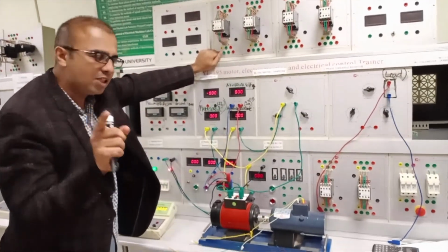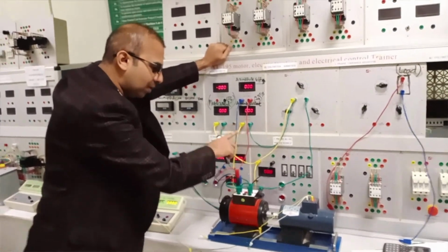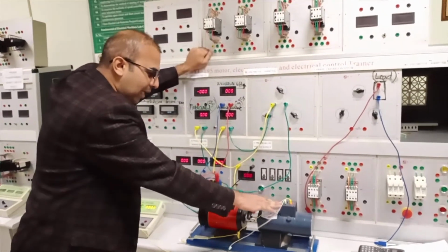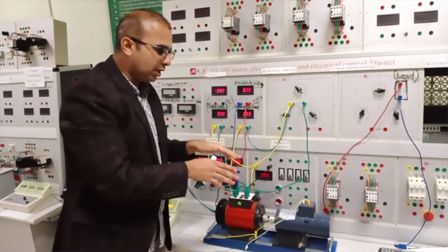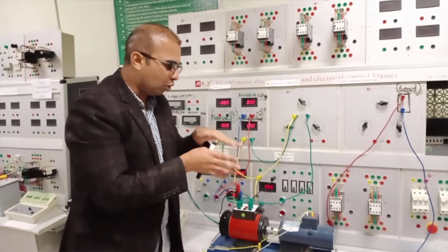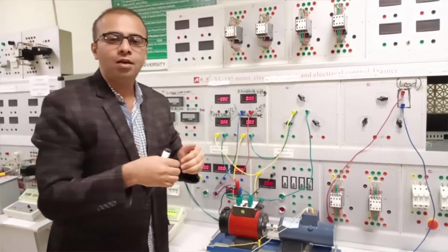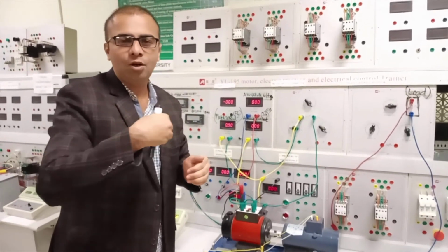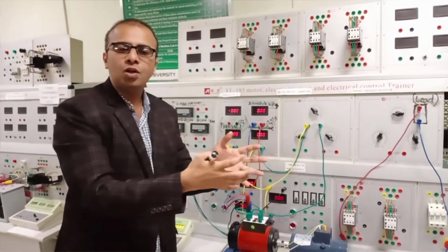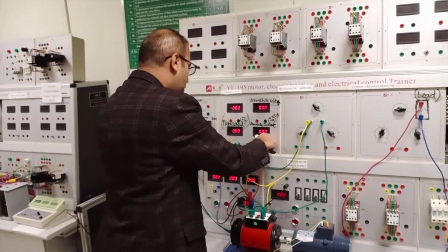First of all, we need to connect this motor with the supply, and this mechanical load is connected with this motor. Before doing this, we have to connect the motor at the no load position. Take the reading at no load, and after that we have to connect the motor with the load. Then we take the load reading and put the values in the formula to calculate the desired results. Okay, now I am going to pull out the wires.